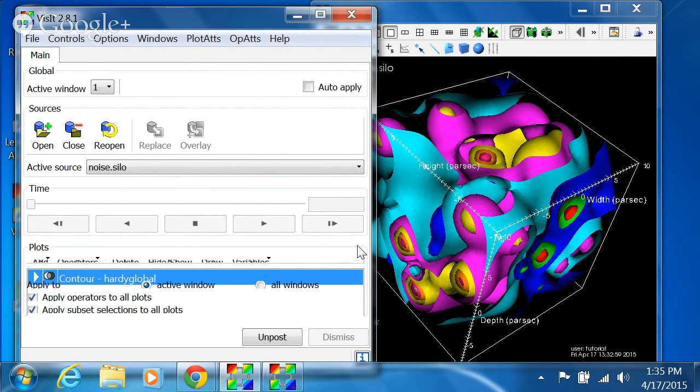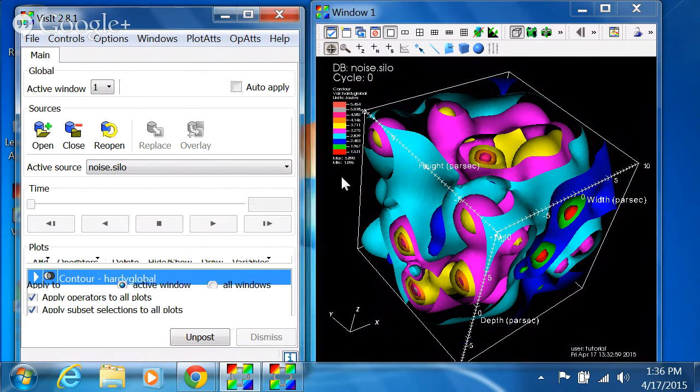If you want to go through the steps, these are very detailed steps with screenshots that will get you there. Then you can change different properties, and every filter and every operation has properties that you can change. You can change the number n, which means how many levels you want to see. That depends on your data. So you have to know a little bit about your data, the data ranges and all that, so that you can set the right range so that your visualization actually means something to you.